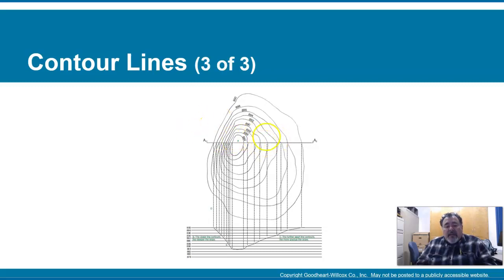So this is not the tip of a hill. This is actually the low point. As you can see down here, 884 is this line, which is basically the bottom, as opposed to over here, this outer ring represents 900 feet. So you can see down here is 884 in height.